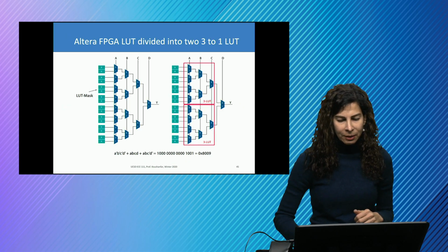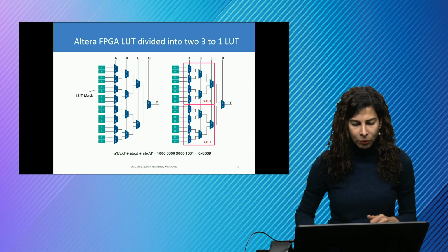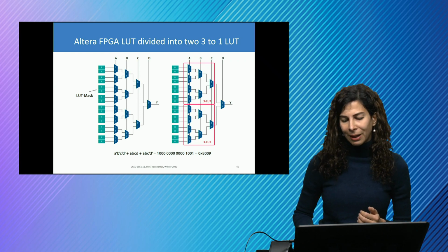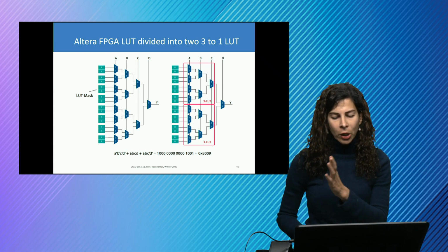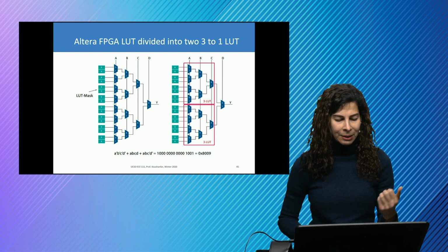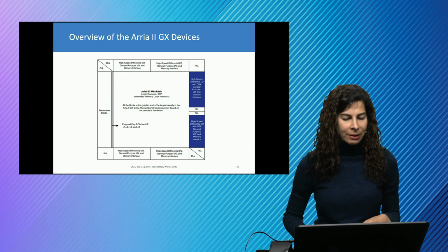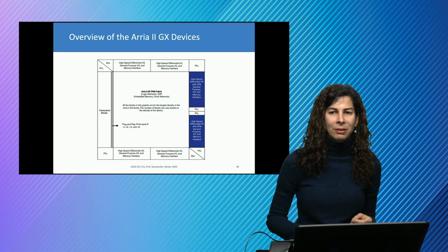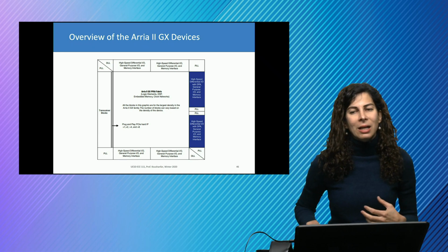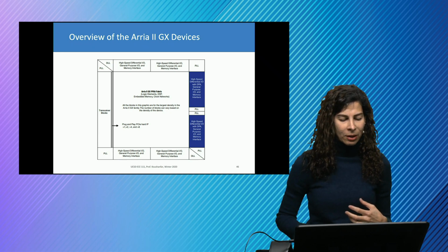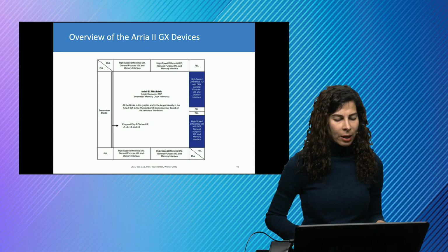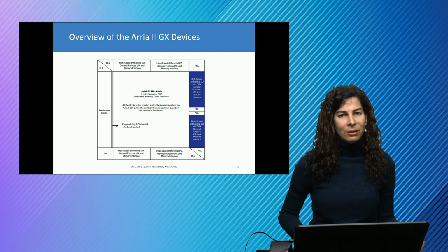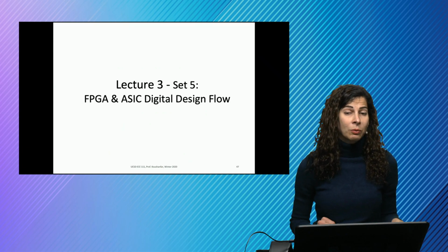The structure is again seen here, but of course, if you have 6 inputs, we have a hierarchy of multiplexers that are 2-input, as shown here. So with 4-to-1 muxes, we have 7 of them to make a 6-input LUT. The device has a large array of these, but it also has some other elements, for example elements for signal processing, the DSP units, and the blocks for phase-locked loops and other elements that are commonly used in design, all on one device.